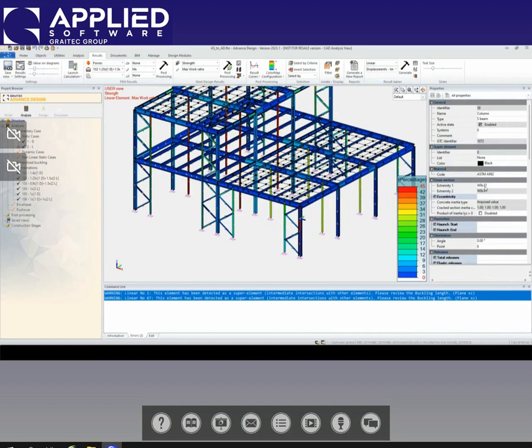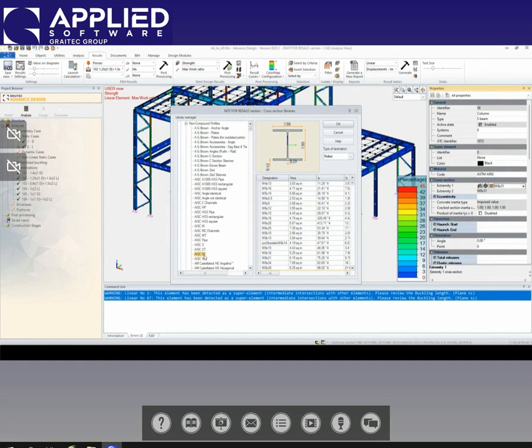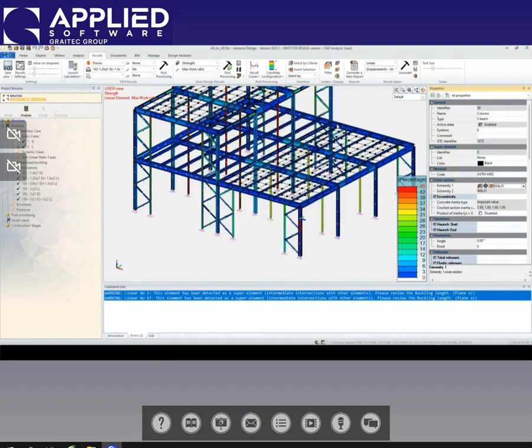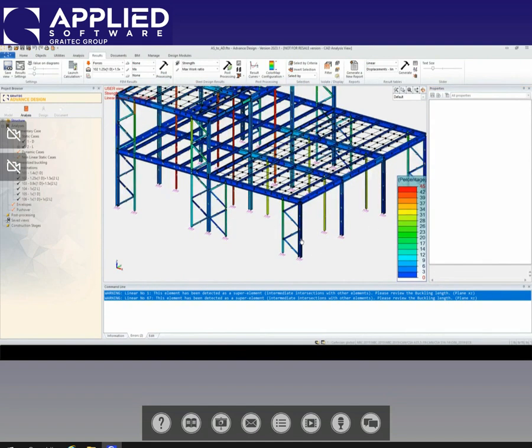It's a W8x31. So I can go to our libraries. So ASTM, that's a W8x31. So for example, let's say for any reason we want to change it to W8x48. Okay, I can click there. Now it's changed to a W8x48, as you see there. You can just double check.